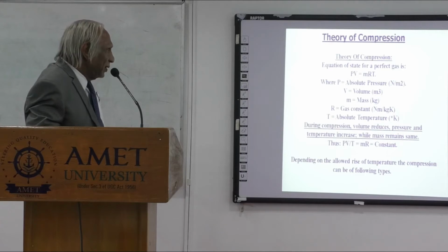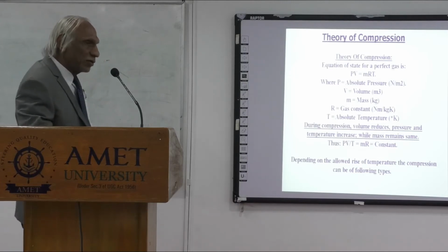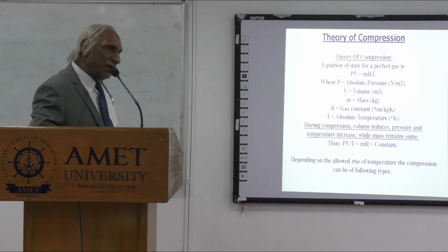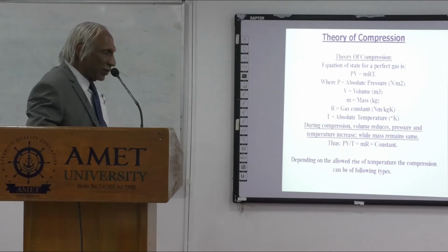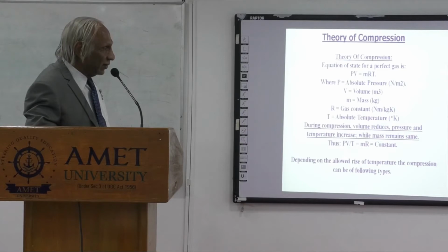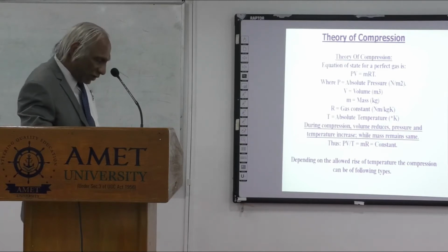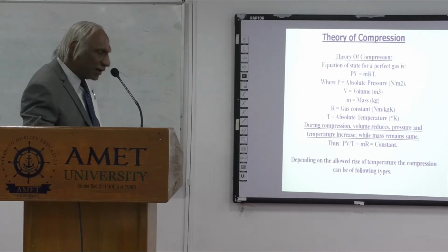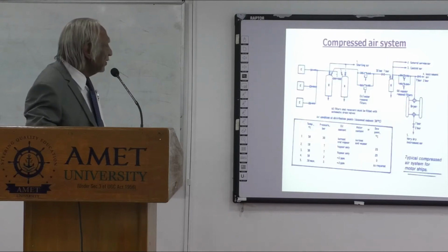The boiler steam is going to run some steam turbine, so the steam flow output should match the feed water inlet flow. So this has to match, and this equipment or valve is controlled by instrument air. There, another application is where your air compressor plays an important role, where pressure is reduced from 30 bar to 7 bar, and 7 bar is subsequently reduced to 2 bar. That is what you see in the general diagram shown in the previous slide.